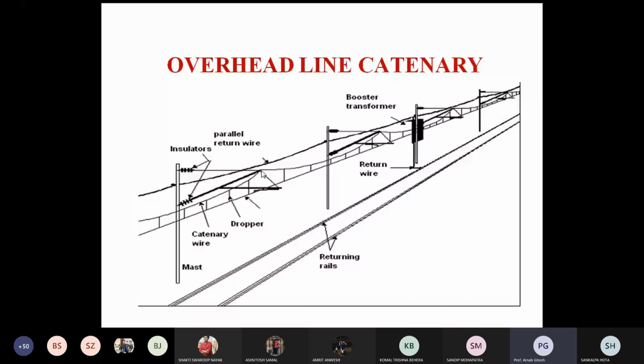So why 25 kV? Basically, the source of the traction system is designed for 25 kV. That's why you have to get the 25 kV. So how to get it? You are normally getting it from the traction substation, where you are using the special type of transformer that is Scott connected and can convert three phase 132 kV to two phase 25 kV.